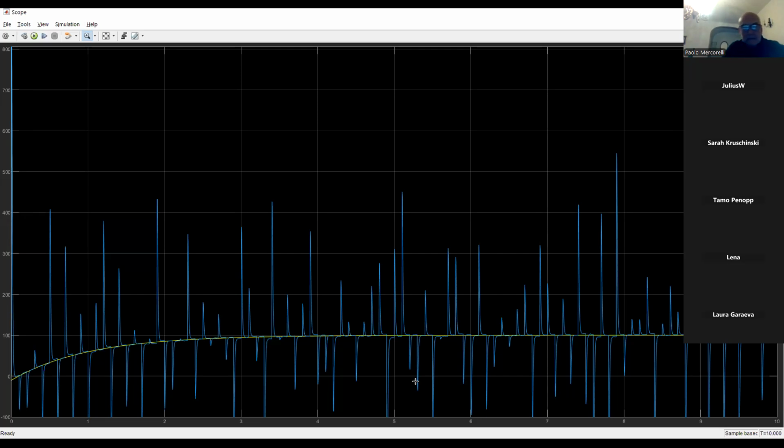Look, of course, sometimes it's not acceptable to have some kind of spikes. Kalman filter can help also in this case. Kalman filter can help also when I don't know exactly the parameters of the system. Here, I assume that the parameters of the system are perfectly known. If I put the same initial condition, I don't see any difference between the x2 and its observed variable.